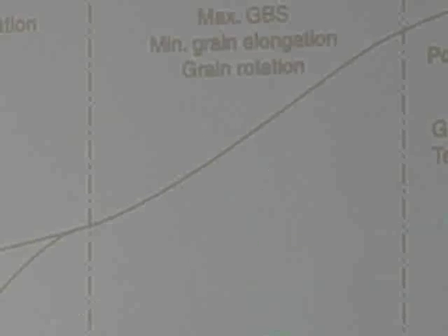Low M values. When you get a high M value, like a half or greater, you get superplasticity. And when you get into just regular creep at high temperatures, you have lower M values. And so there's different types of creep.